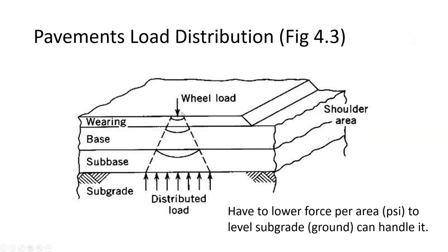And in the pavement, this is what we're doing. This is actually from your sophomore textbook, that we've got a wheel load here, and it is just spreading that load out as it goes through the pavement. Right, here's our surface of the pavement down through the subbase, right? And that force radiates through there. It's kind of a cone shape.